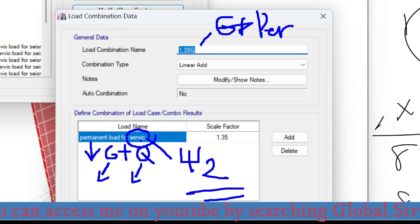But in the case of seismic combination, we should use the live load reduction factor phi 2. We need to multiply this by 1.35 because we are defining the load combination with reference to the gravity load, which previously we didn't factor. This is a service load, which is why we are applying the scale factor of 1.35.